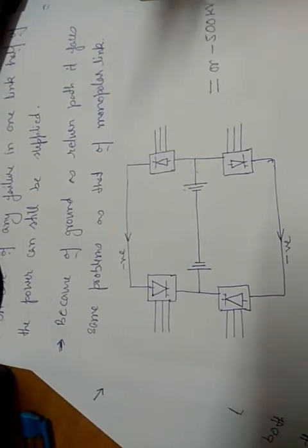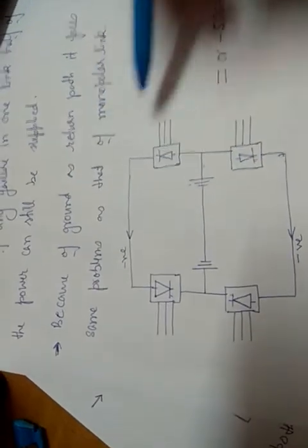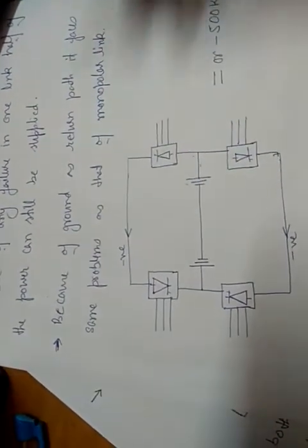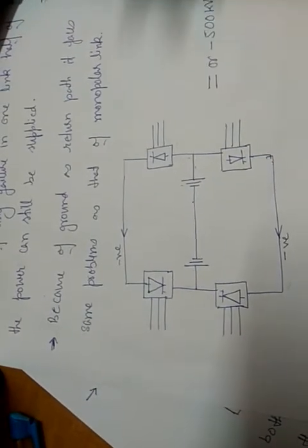Okay, so in case there is any failure in any link, half of the power can still be transferred through the other link, means reliability is still more in homopolar, but still it has got some problems because of this return path. So that is why it is not always preferred.